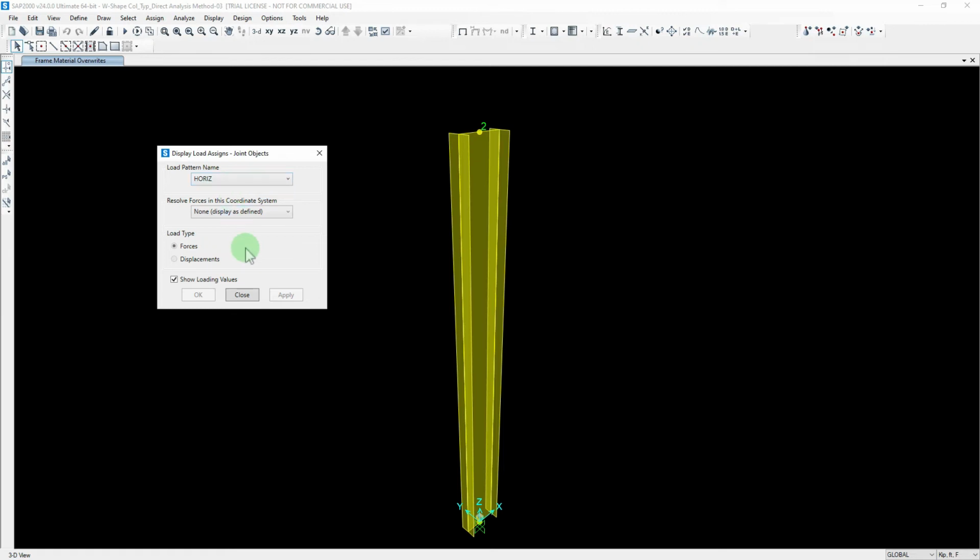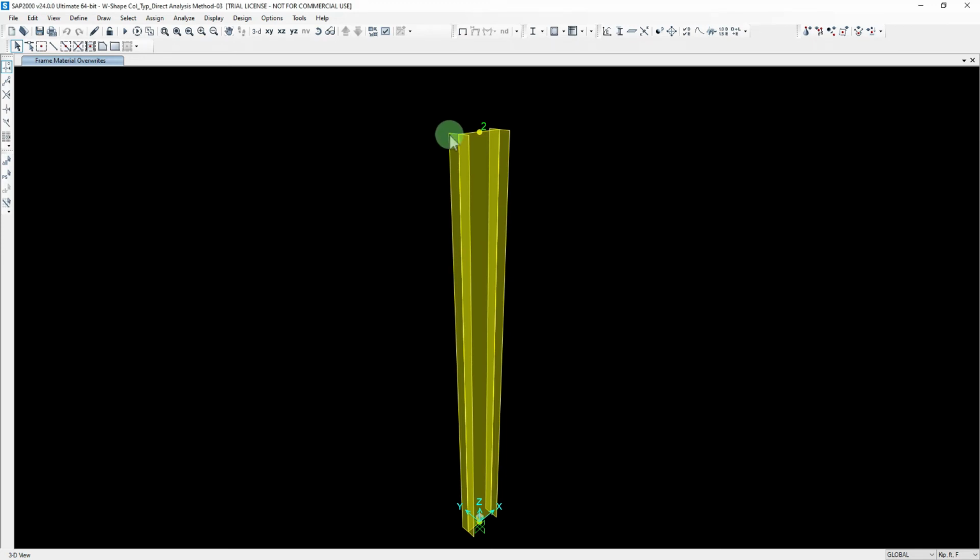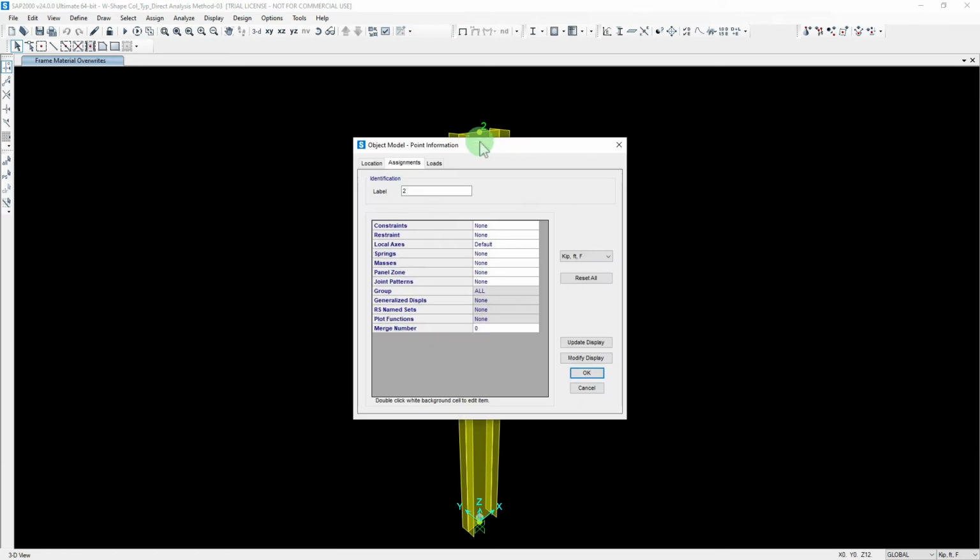So here I could say, if I had any load in there, it would show, but say I didn't put any loads, and therefore this is not active. So this is a way for me to verify whether or not I put any load. So I know no loads are on this structure right now, and I could also select the element and right click, and I don't have any loads shown here.